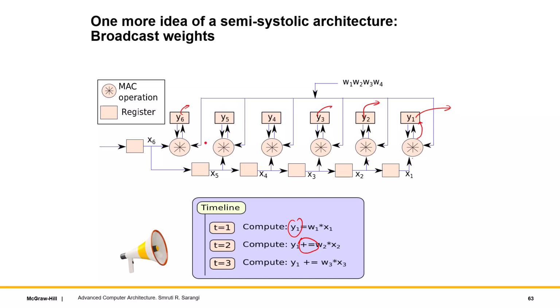So here of course broadcast is involved, and again we are not happy with the broadcast mechanism, because what will happen is that it's the same wire, right? So the same wire is like one long wire connected to both here, here, here, here, and so on. It will have a massive RC delay, because there will be some capacitance over here, some over here. All of that is in parallel, so it will add up. So essentially charging the entire wire will take quite some time. So again, we are not very happy with this design, but this is still a valid alternative design. So in this case, by broadcasting weights, we can still get our job done.